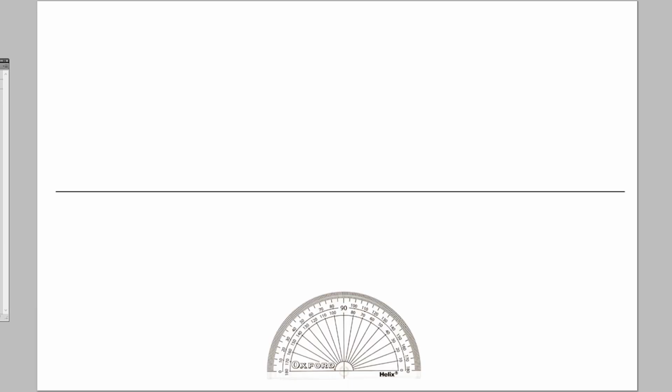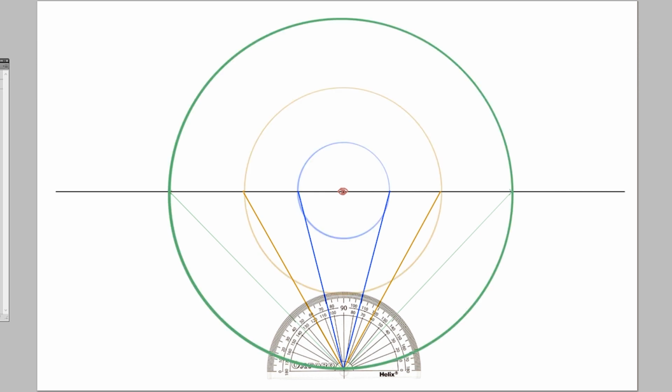Here we start, as we always do, with a blank page that we've drawn a horizontal horizon line on. The first thing we add are our diagonal vanishing points and our center of vision. Again, deciding how far away our viewer is from the page. The next thing we do is find our 30-degree vanishing point and our 15-degree vanishing point. Again, expanding these into cones of vision, as these are going to be useful in our perspective construction moving forward and avoiding distortion. Now that we have our perspective grid all set up, we can get into our first construction.